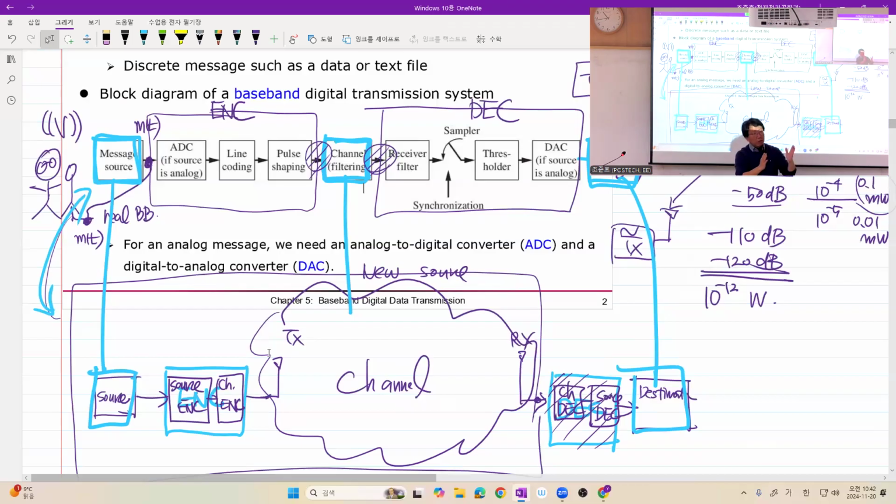And its carrier frequency, suppose it's 3 gigahertz, even though signal bandwidth is 100 megahertz. Now, according to the sampling theorem you learned in signals and systems, you may at least require 6-point-some gigahertz sampling rate. What does that mean by gigahertz sampling rate? You have to sample 10 to the 9 times within a second.